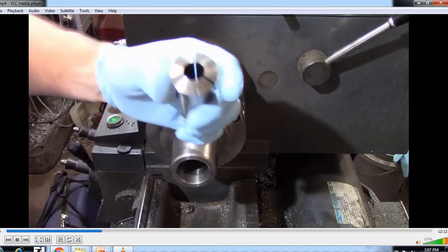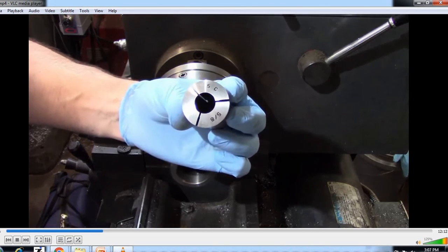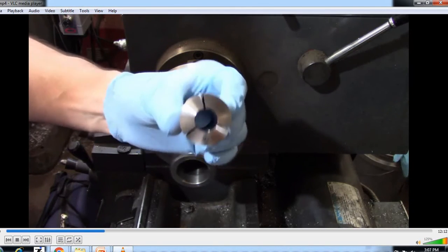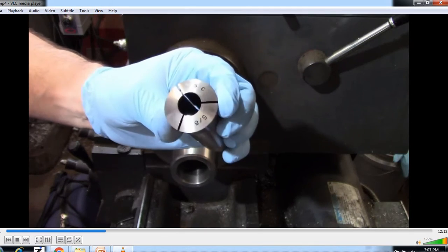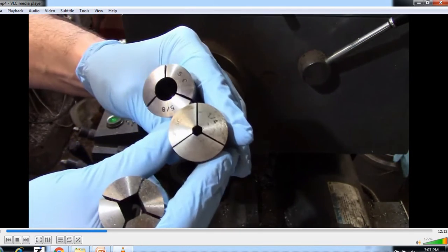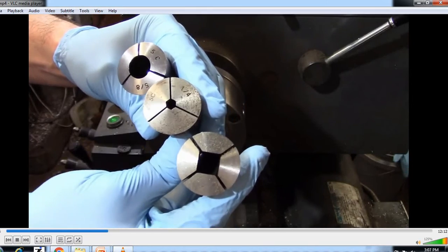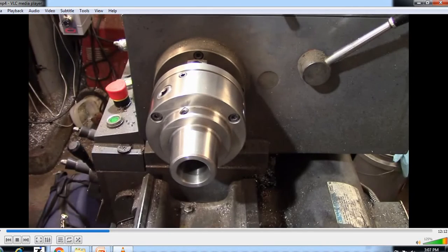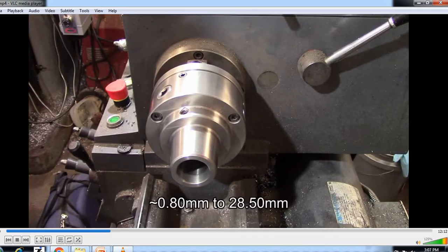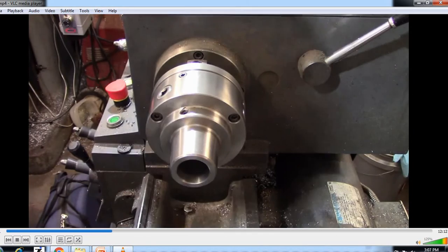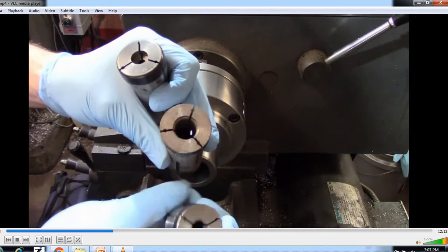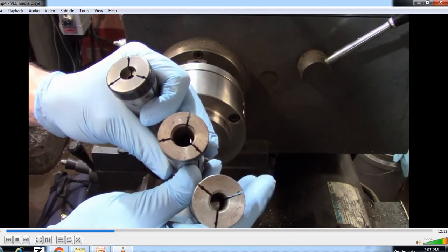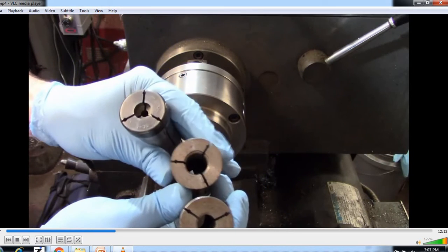By far, at least in the United States, the most commonly used type of collet used on the lathe is the 5C collet. 5C collets are available to hold round, hex, and square stock, and have a round capacity from 1/32 of an inch up to 1 1/8. Machinable collets are also available for making special fixtures or sizes that are not commonly available.